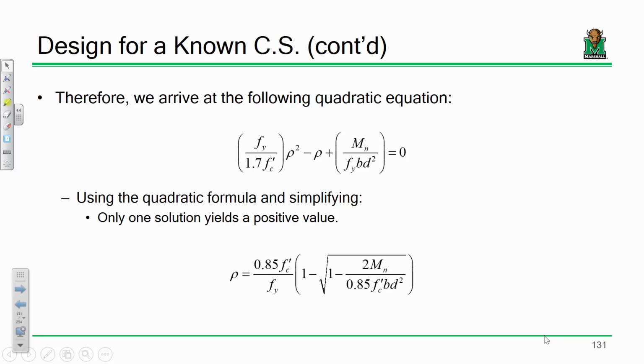Unitless. They are unitless. There are no units. They're a percentage, right? So make sure that the stuff that you plug into the reinforcement ratio makes sense, okay? So, for instance, if you have f'c in ksi, and this is in inches and this is in inches, your moments need to be in inch-kips, okay, not foot-kips. So just be aware of that.